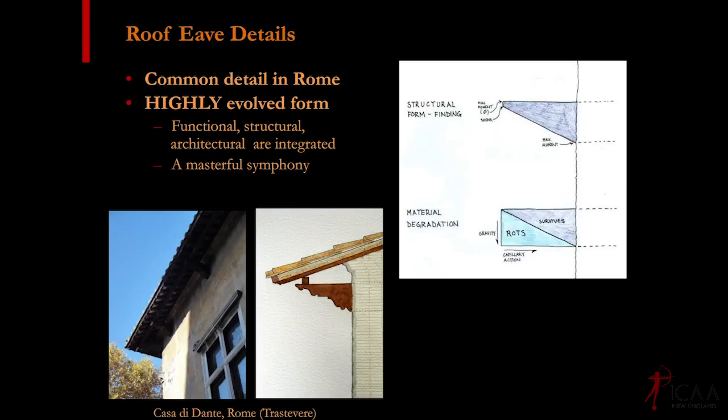And the reason you cut it off is actually preventative, because when you have a straight member that's out in the rain, you've got all this end grain to absorb water. And then think again about our gradient of water. Gravity is taking that water down, while the end grain, wicking, capillary action, and absorption are taking it in. So when you end cut these and expose the end grain to the weather, this tends to be the pattern of rot. And as the owner of a 1914 bungalow that had straight cut joists like that, I can personally testify that that's exactly how they rot. So you want to cut off the cancer before it infects the whole structural member.